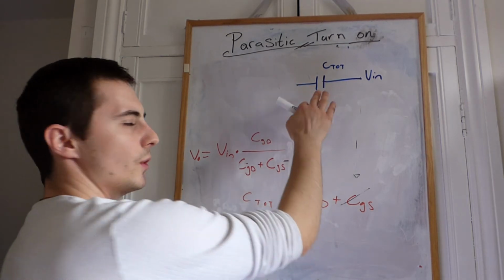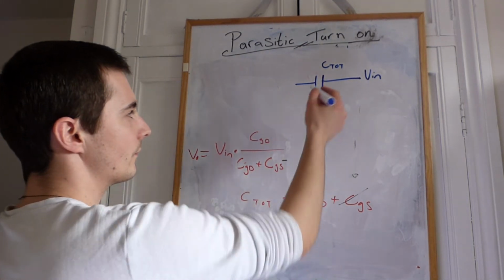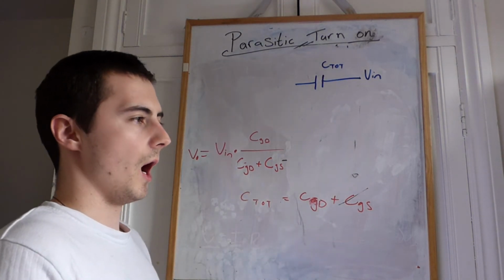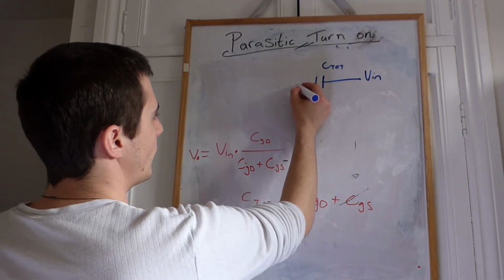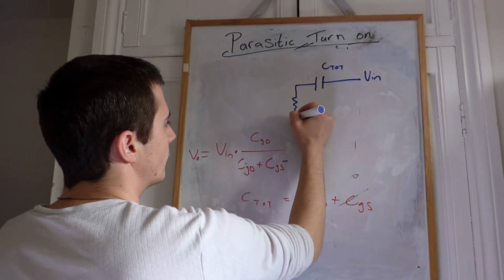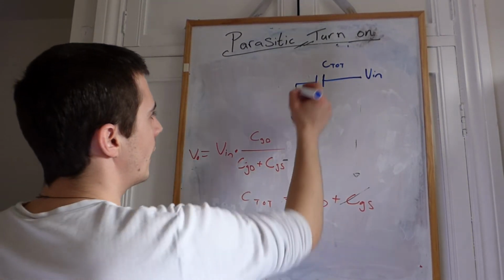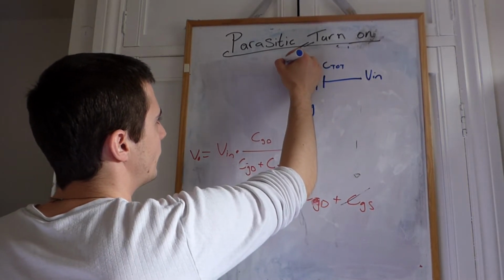So that's similar to what you would do where you would have the Thevenin equivalent resistance. You would have some resistance there. It's usually like the internal resistance of a power supply, something like this. And then we reconnect our load, which was RG, so our gate resistance. And what we're actually interested in is the voltage at this point here.